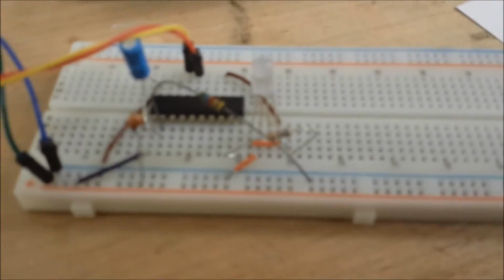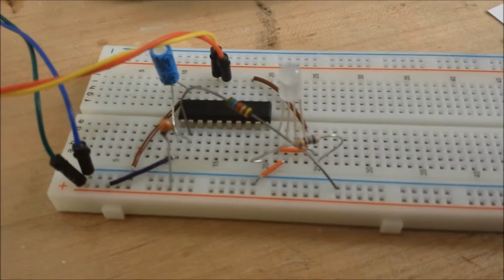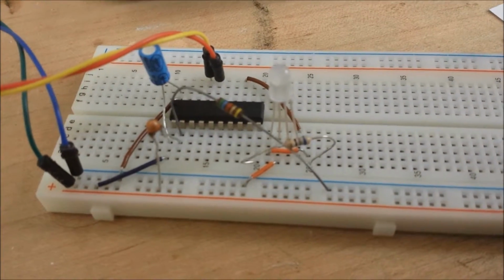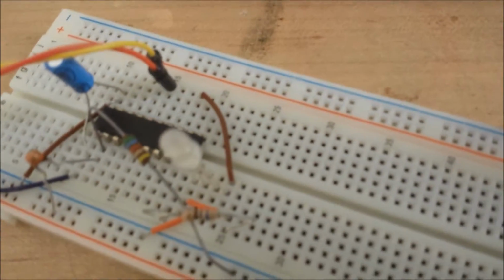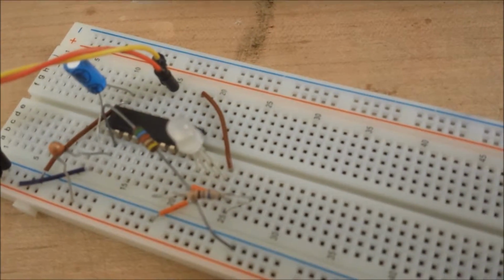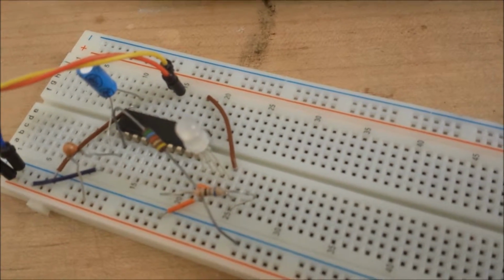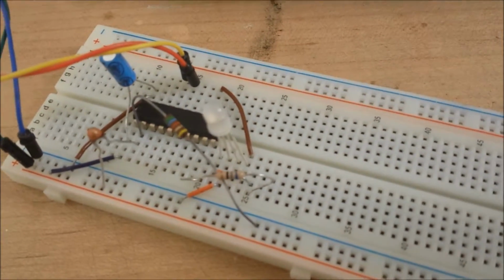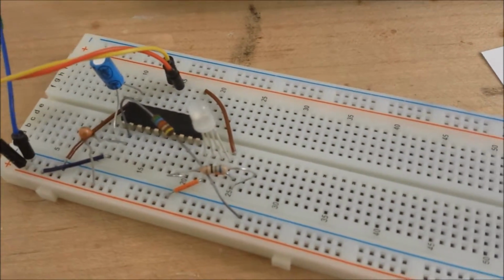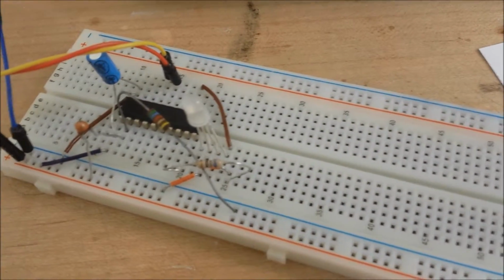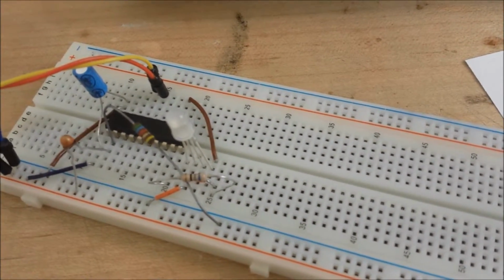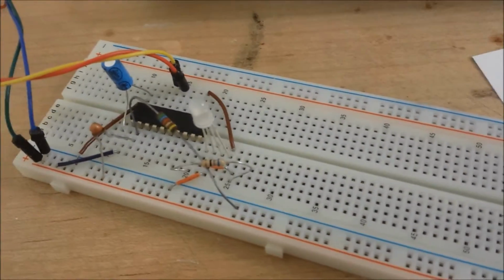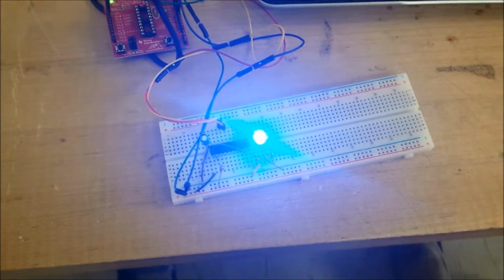Here, pin 2.2 is connected to the red pin of the LED, and it will output the value of CCR1 to that red pin. Pin 2.5 is connected to the blue LED, and depending on the value of CCR2, it will change the output and therefore change the brightness of the blue LED. Combining the red pin and the blue pin, we could change the gradient of the LED from blue to purple to red. Let's demonstrate the mood ring in action.